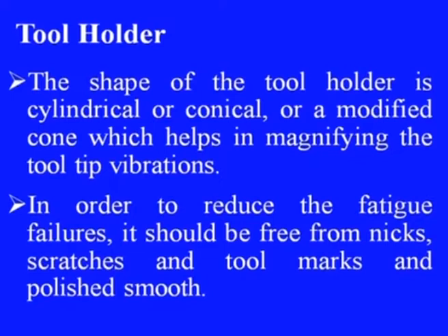Thus, the shape of the tool is determined according to the optimization of the tool vibration. In order to reduce the fatigue failures, it should be free from nicks, scratches and tool marks and polished smooth.